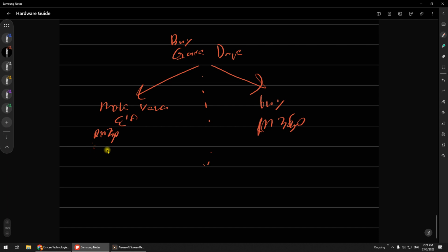For this case, you need to have multiple power supplies. This is a must if you want to make it on your own. Like I said before, it is for isolation. The power supplies need to have different grounds, if not, it will become a short circuit. Or you can buy it. Buying is quite expensive, around 350 ringgit. So this is your choice.